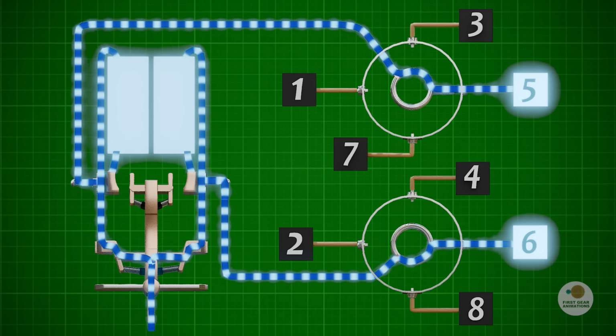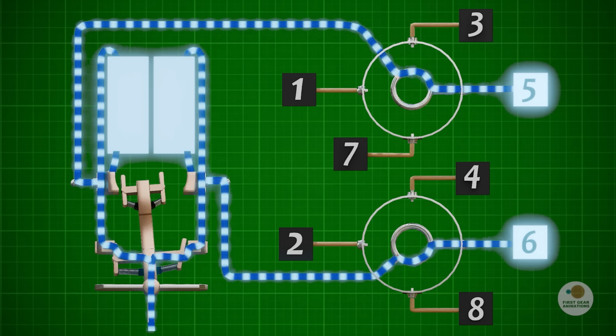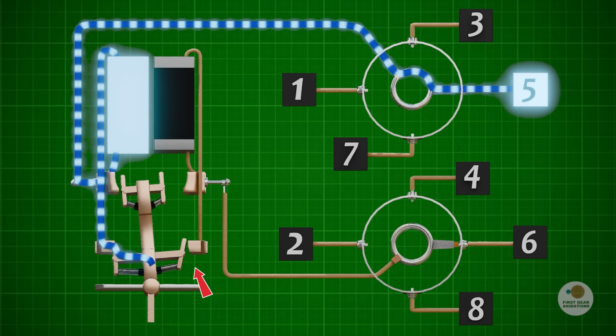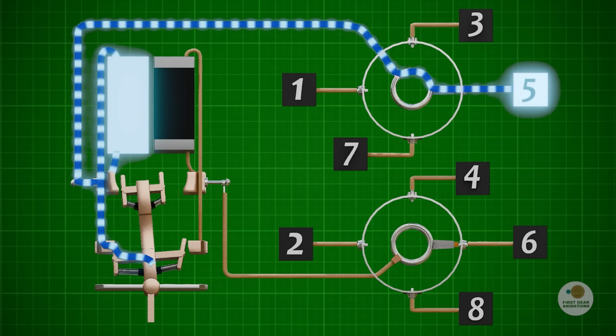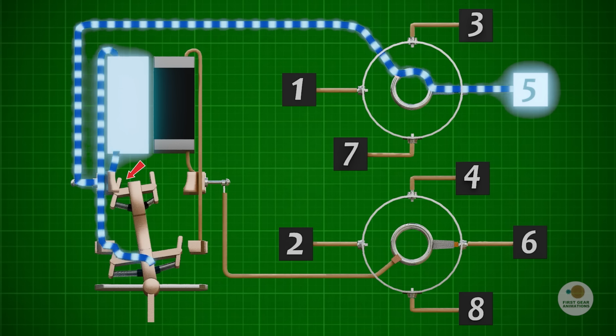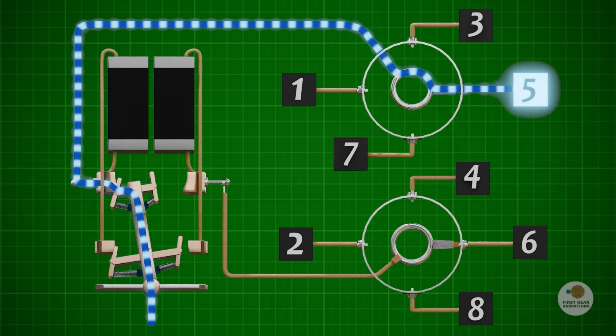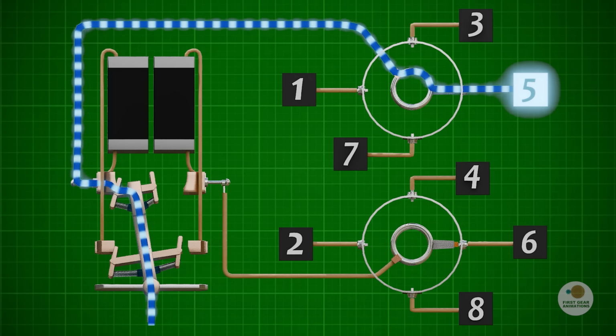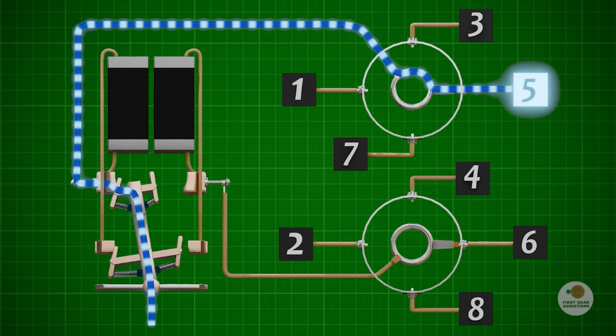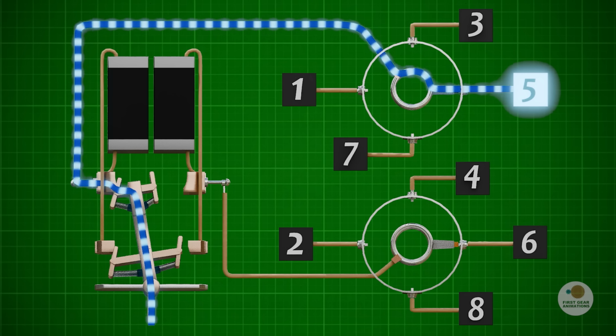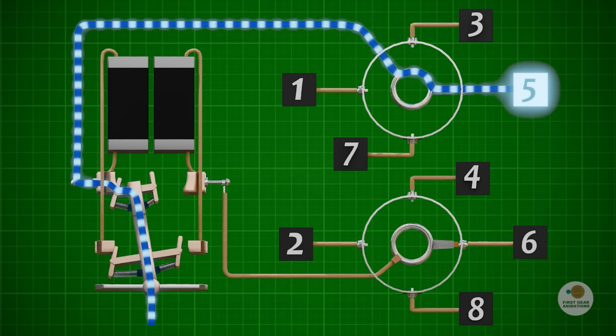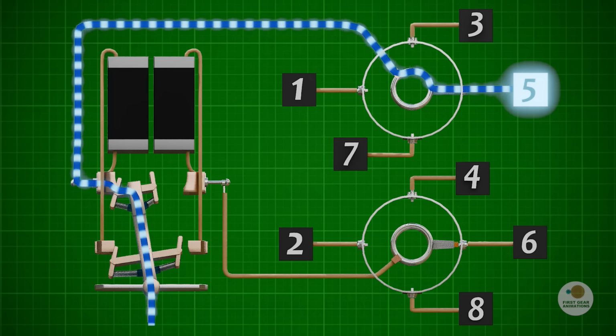As the diverter approaches the new tap position, the first transition resistor is bypassed. Once the new tap connection is fully established, the second transition resistor is also removed from the circuit, allowing the load current to flow directly through the new tap. This entire switching process happens very fast with no interruption to the power supply.